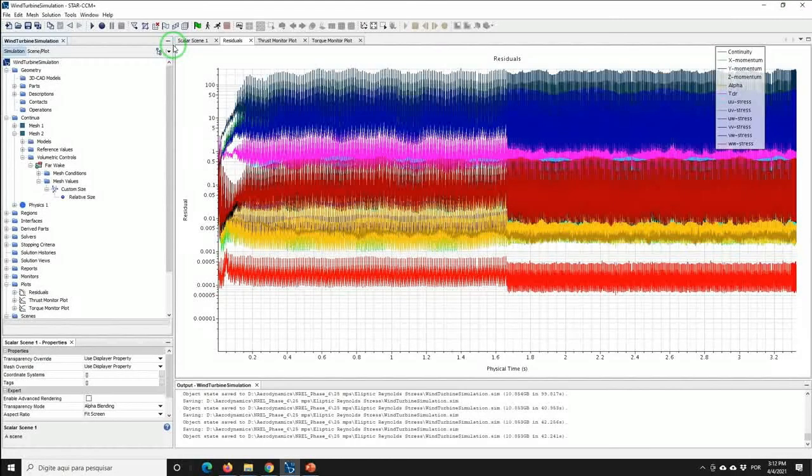At the end we have the post-processing, okay. It is worth mentioning that the computations are performed on a desktop computer consisting of 64-bit Intel i9 processors with a frequency of 3.6 gigahertz and 64 gigabytes of RAM. The simulation takes almost 12 days to finish because we are using the Reynolds stress turbulence model. We could use some turbulence models that would take much less time. I'm going to explain further the various types of RANS based turbulence models in another video, where I'm going to discuss these aspects also.